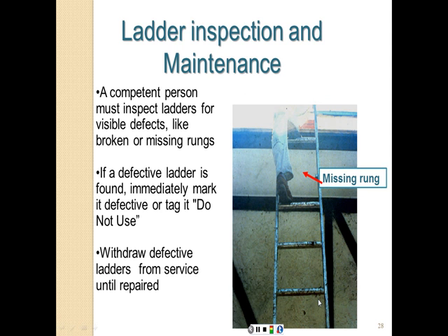If a defective ladder is found, immediately mark it defective or tag it "Do not use," and withdraw defective ladders from service until repaired, because again they're going to remain a falling hazard until they are corrected.